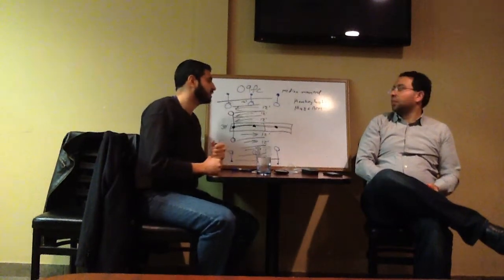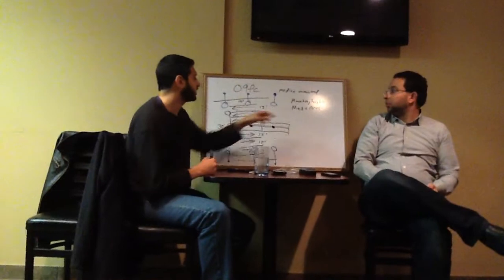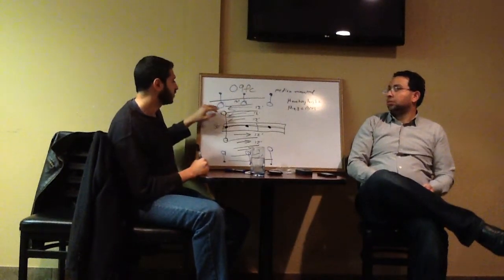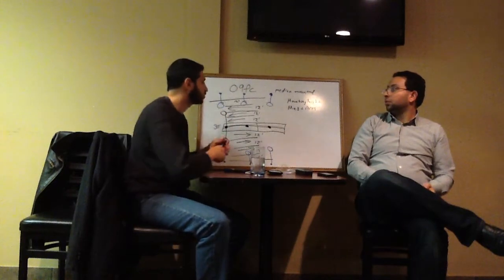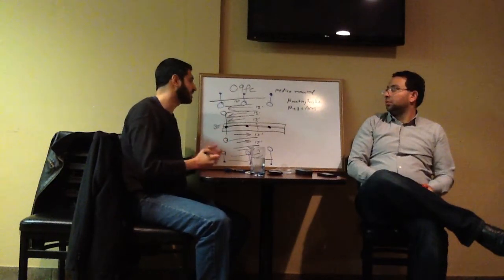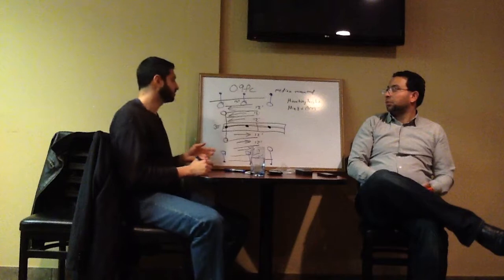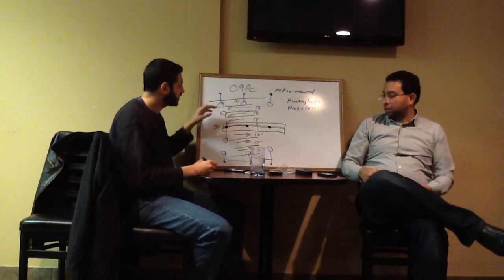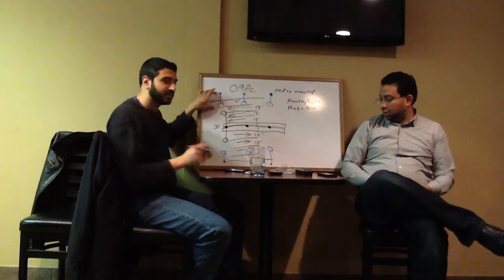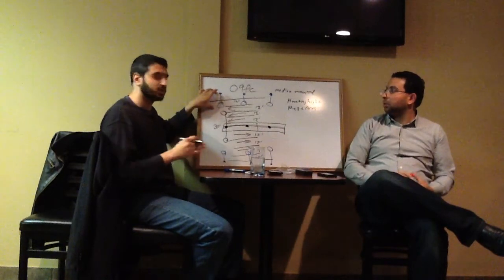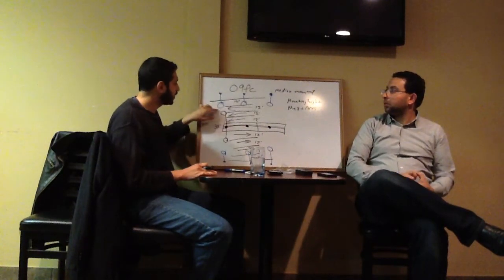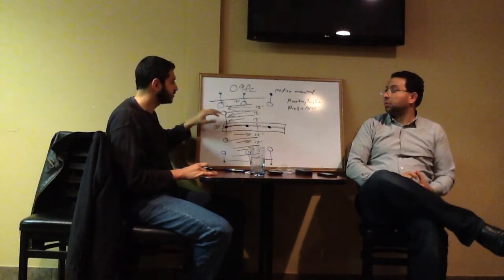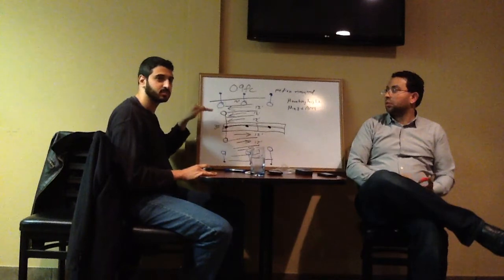The next thing is the mast arm. That's the arm that's mounted on a pole that holds the luminaire over the roadway. Depending on the size, 6 foot, 12 foot mast arm. One thing you want to remember is, depending on the numbers you get when you run the calculation, you really don't want the light over the roadway, because just in case something happens, you don't want that light falling on top of the traffic.